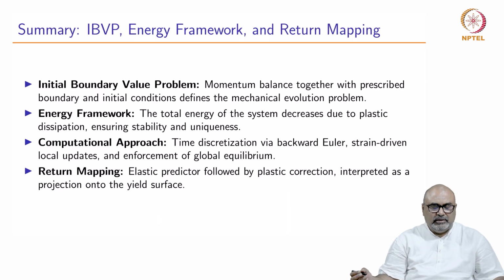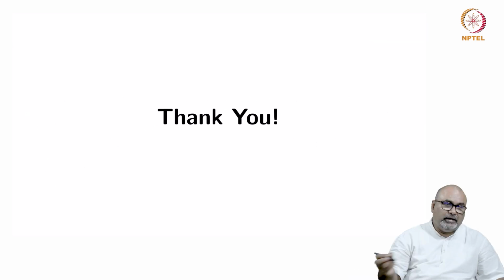So, in summary, in this presentation we have discussed how to define the initial boundary value problem, what the energy framework is during a plastic process, and what computational approach we need to follow. We discussed how we define a time discretization using a backward Euler scheme for a strain driven problem, how the global equilibrium is enforced, and how the elastic predictor plastic corrector technique is used for return mapping for both isotropic hardening and combined hardening cases. In a one dimensional problem we have discussed this approach. Thank you for your attention.